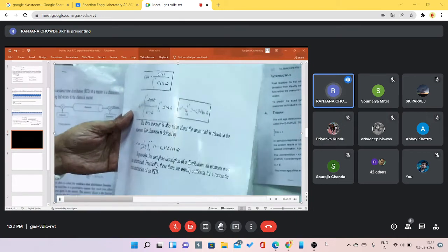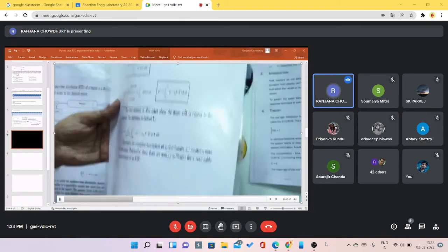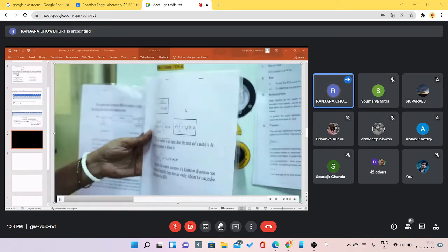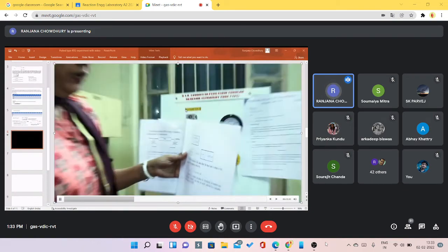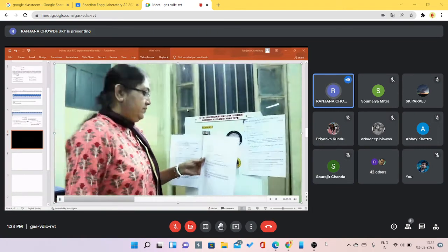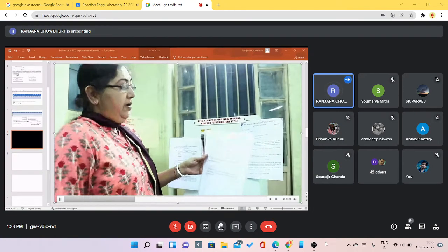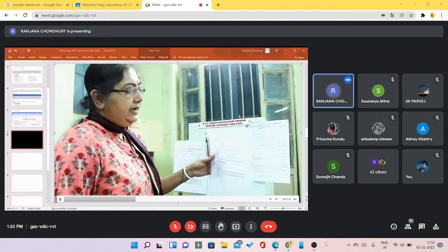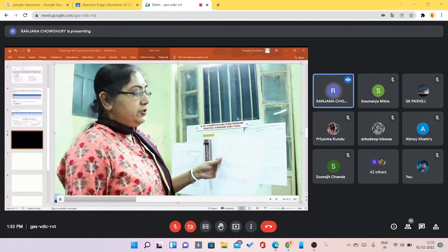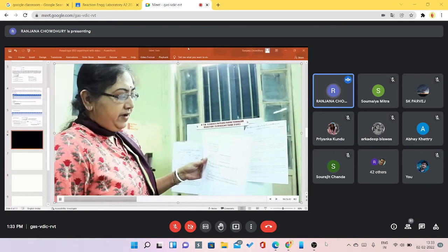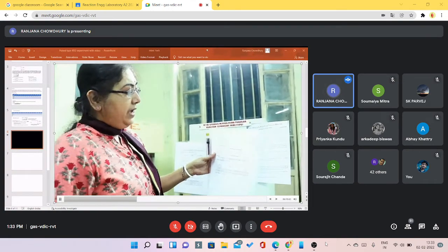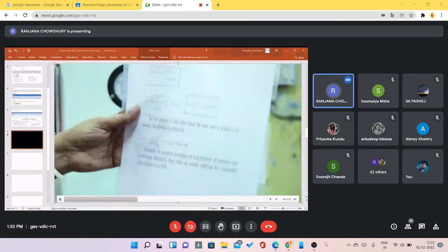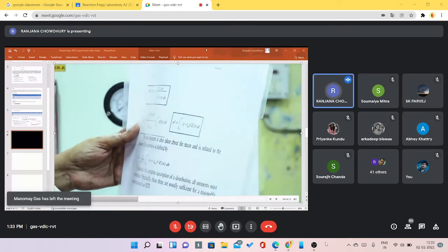Now, we cannot go on doing the experiment for infinite time. So, we will do the experiment for a long time, say 20 minutes, and for the denominator, we will numerically integrate this. So you will measure the C(t) values, and from that, you can obtain the E(t) value, that is, the residence time distribution function value.